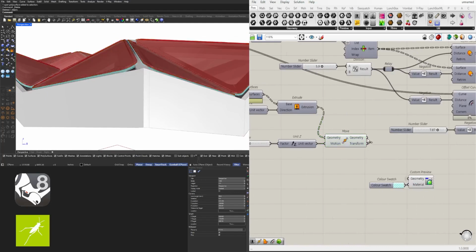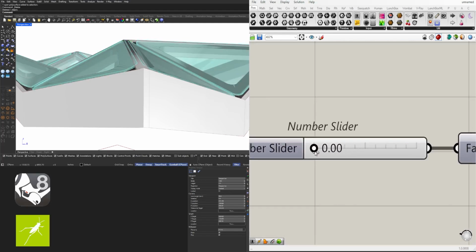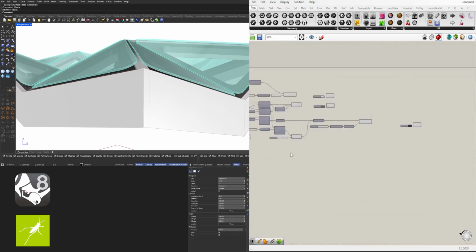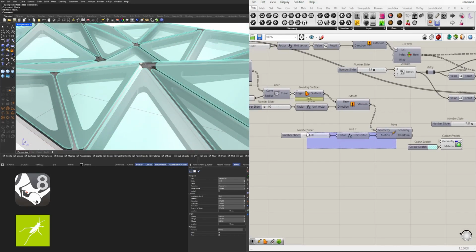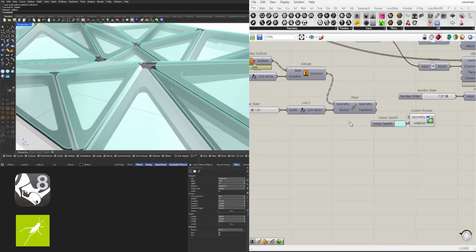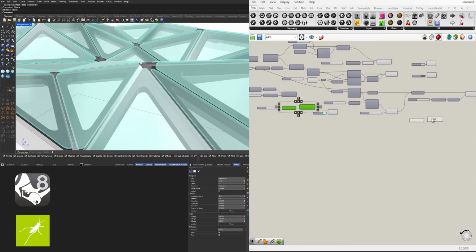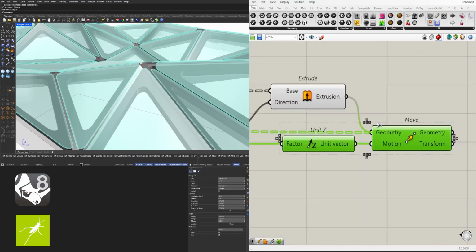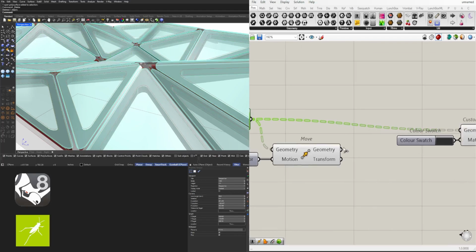Do you see that? Now, obviously, we need to override this again, so we can see at what point it intersects with it and we can be past it. So let's say if it's 1.5 here, well, we know we need to do that as well to the frame here. So I'll take this modification of moving it up by this much, and I'll copy it over there. But I'm actually going to undo that. I'm actually not going to copy the slider because I want to share that slider with the frame. So if I just take this, tap Alt, it will keep this one plugged into the copy. And now we don't necessarily have to create or retie a different one. It's just going to move it up by the exact same amount, and we can override this.